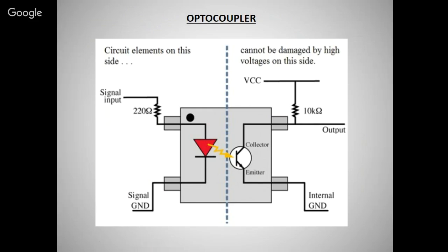Now, an optocoupler I have used. Why is the optocoupler used? Anyone can say, you are from an electrical background, where is the need of the optocoupler? For the firing of the SCRs, basically for the load. Yes, we can fire it for SCR, but there's one thing missing, the most important thing of the optocoupler. Optical rays. Isolation.